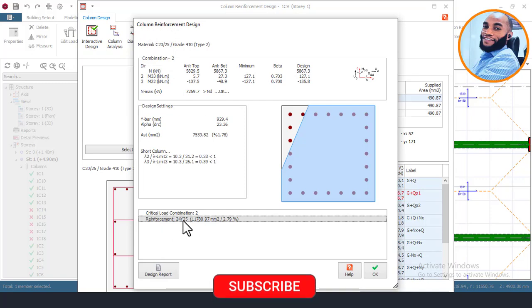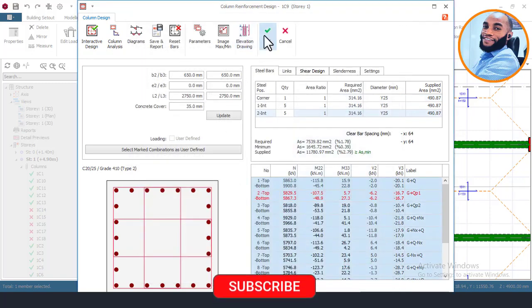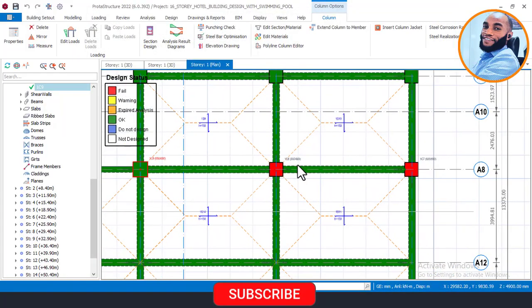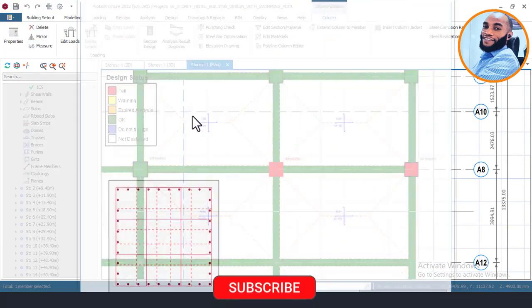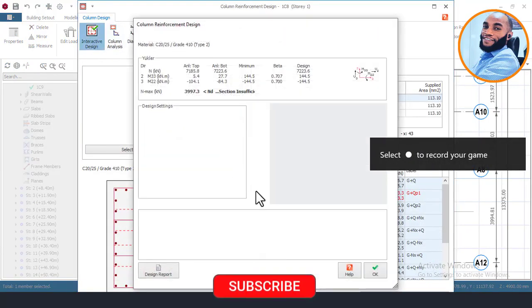Okay, that's fine. There are 24 number of Y25, that's fine, and I'll click on okay, and again okay, final okay here, and that column will be okay. I'll come again, click on this other one here, right click and then click on section design, and I'll click on this place here, design first to see why it's failing.